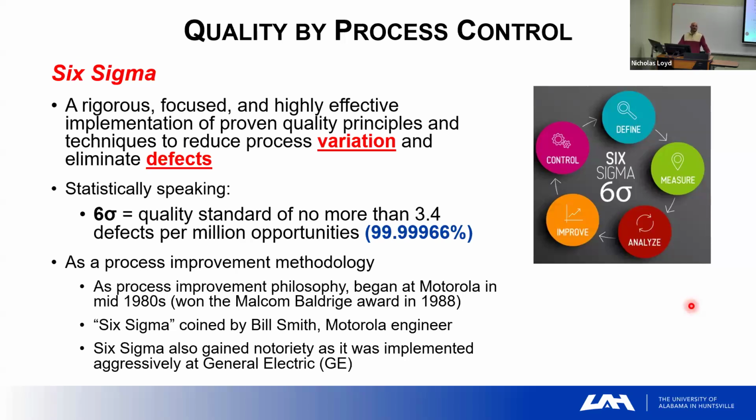And then plus or minus 3 standard deviations, 5 foot to 6'6", 99.74% of the population. All the way to plus or minus 6 standard deviations captures 99.99966%. Which means if I have 6 sigma level quality, I'm only making a defect every 3.4 million opportunities. So they use the term 6 sigma to basically say we're striving to eliminate variation and defects to have